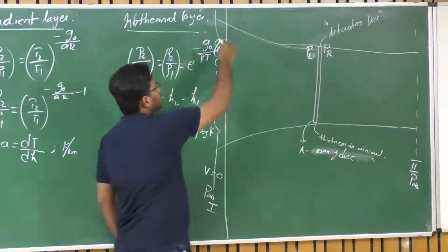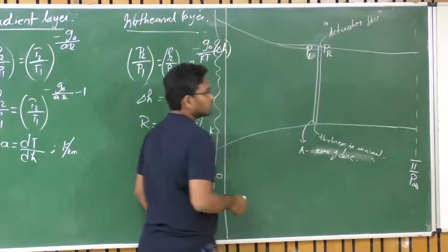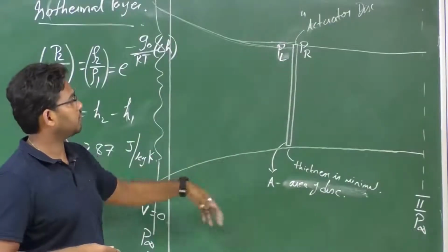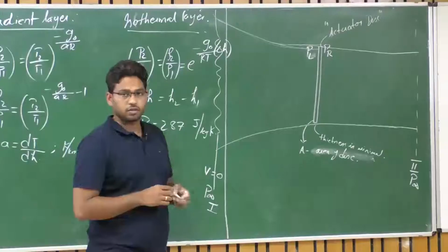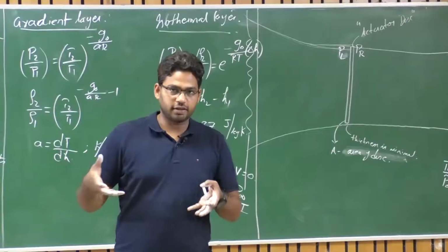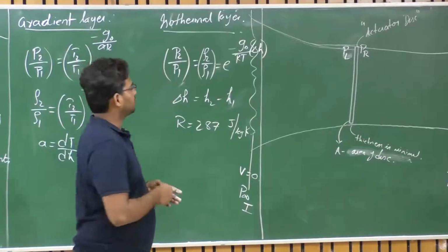And these two particular lines represent the boundary conditions. They are nothing but the streamlines on the boundary, or the circumference, of the stream tube. What is a stream tube? If we have a bunch of these streamlines together, then we can consider it as a stream tube.